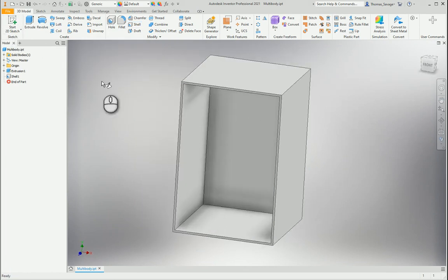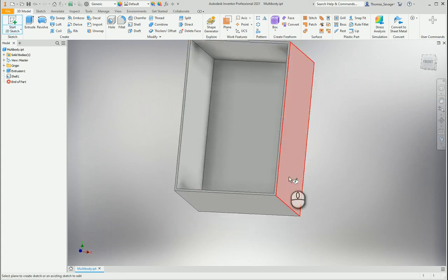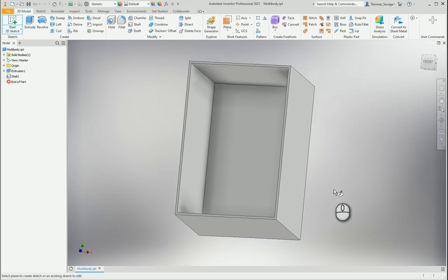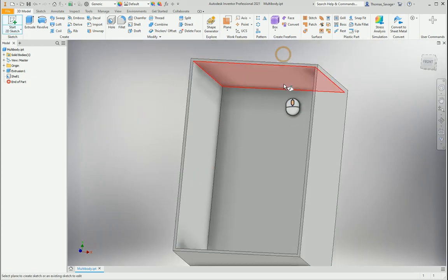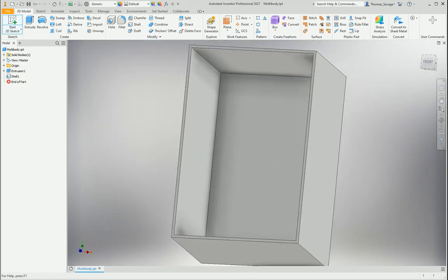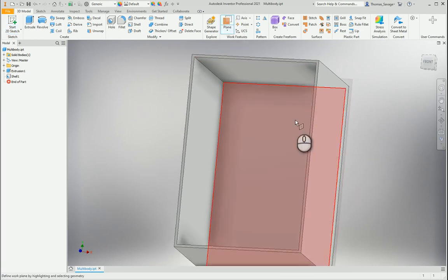So now we're going to draw the drawers. We're going to have 8 drawers in this cabinet. So if I do 1500, which was the height, minus 40 for the top and the bottom, because we shell 20, so that would be 20 at the top, 20 at the bottom, then divided by 8, so we want 8 drawers, equals 182.5. So I'll draw the first drawer.